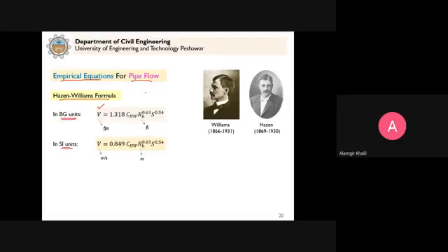So that is why this Hazen-Williams formula was developed, to avoid the trial and error procedure that is given by F. You can see here, there is no F. There is no friction factor. Later on, we have the Moody's diagram or Haaland equation that simplify, but that happens later. In the beginning, when we only worked with the Colebrook equation, it was trial and error to calculate the F. So that's why scientists and engineers came up with these empirical equations to simplify the procedure. Clear? So one of them was the Hazen-Williams formula.